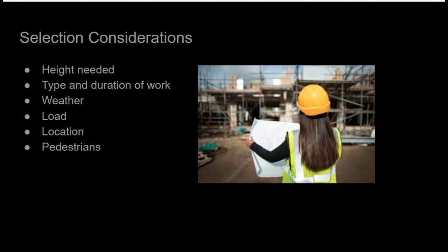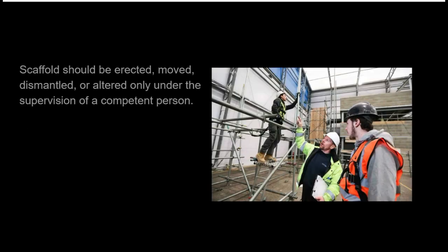Many factors go into the selection of the right scaffold for a job. Considerations include the height needed for the job, as well as the type and the duration of the work. Weather must be considered, as some scaffolds are more stable than others in inclement weather. Load, location, and the likelihood of pedestrians passing underneath must also be taken into account.